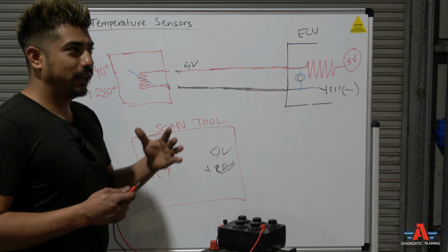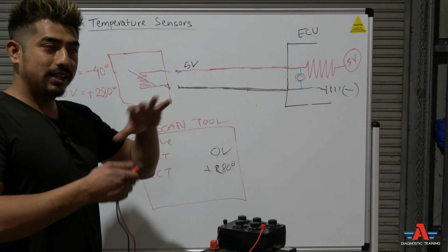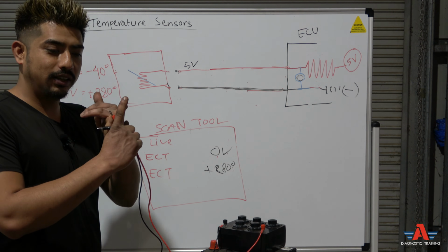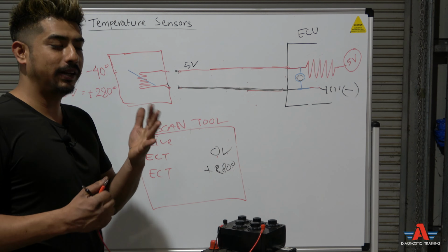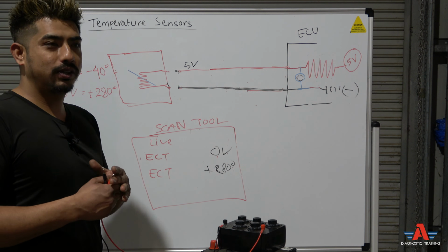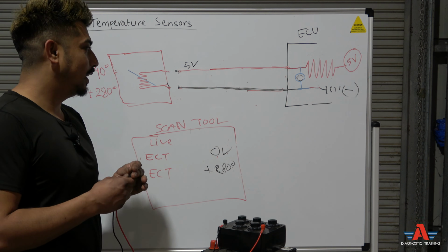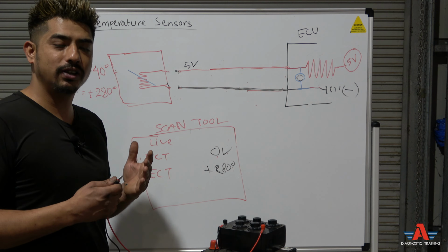So far as I know, this is my understanding. When it's really cold, obviously the oxygen sensor is not functioning, so it's not trying to correct the fuel trim. Second, maybe the engine was waiting to see a little bit of temperature rise before it starts correcting the fuel mixture.